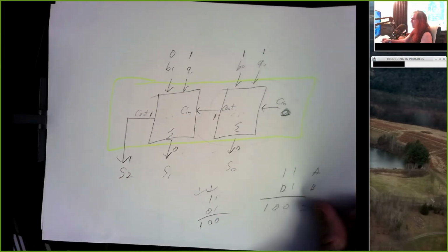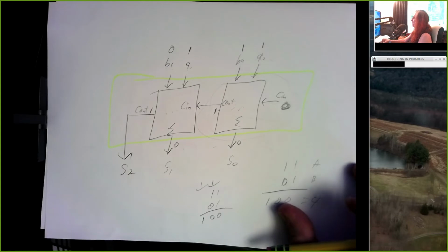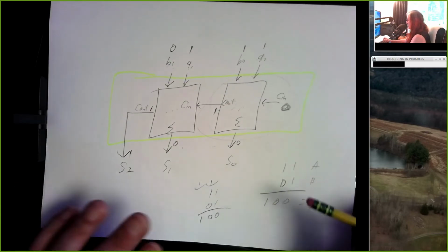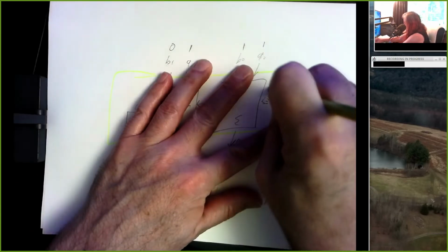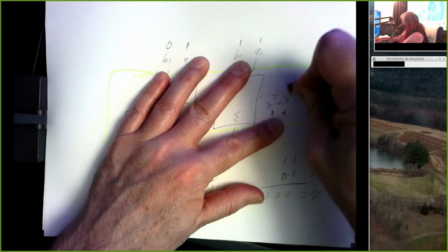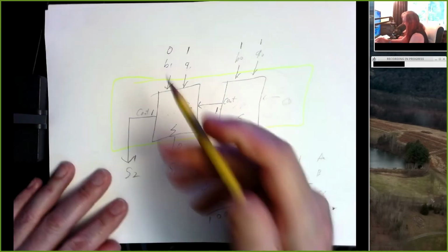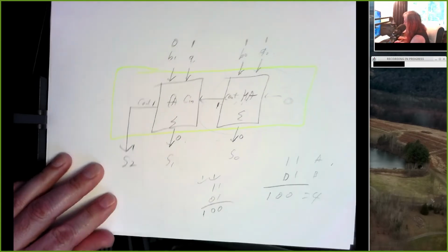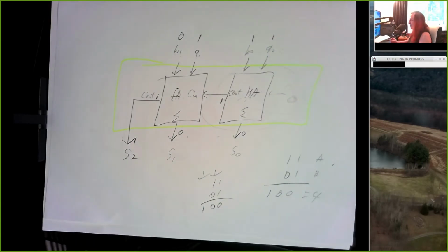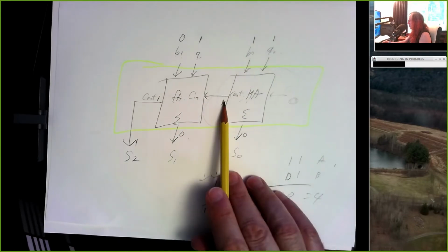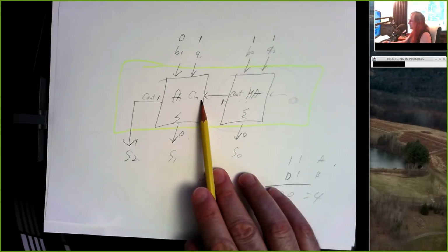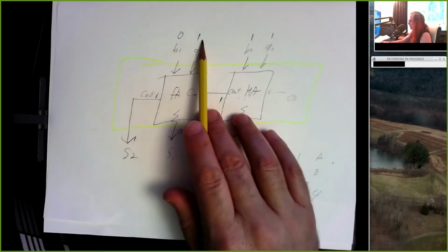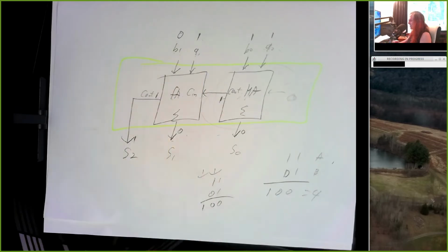So your final design for experiment 2 will be to build a pair of circuits. This is going to be a full adder. This is going to be a half adder. The half adder takes in 2 bits, generates a sum and a carry. That feeds the carry of the full adder, which takes in that carry in 2 bits, generates a sum and an outgoing carry.